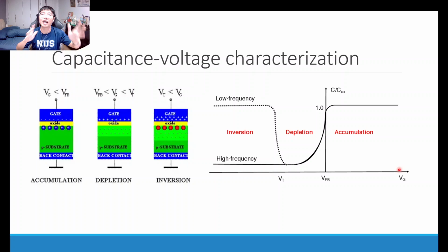Okay. So now, enough talking about interconnects. Now let's talk about the gate dielectrics, or dielectrics in general, but I want to specifically focus on the gate dielectric, also known as the gate oxide. So I'd like to bring once again to your remembrance this CV, which stands for capacitance-voltage graph, of your MOS stack, so your metal oxide semiconductor stack. Do I need to explain again why this curve comes about? Okay, maybe I'll explain again because I later want to talk about how certain defects in the oxide will alter this curve.